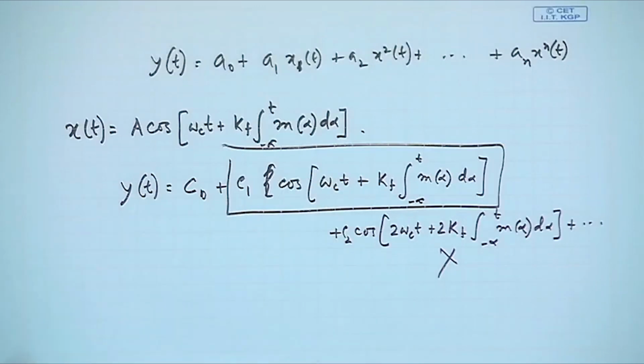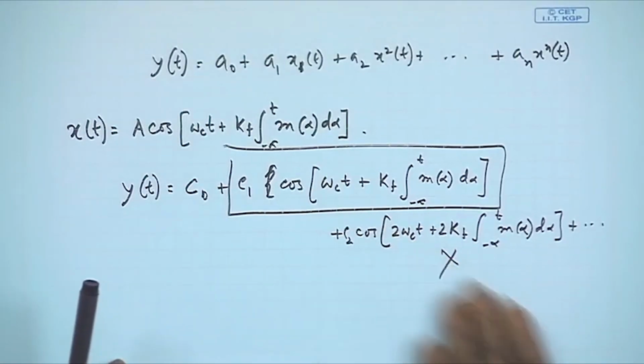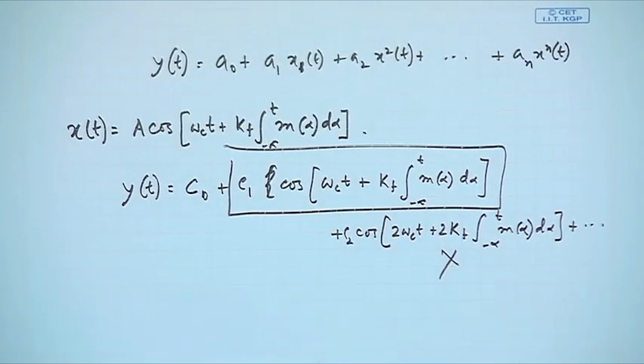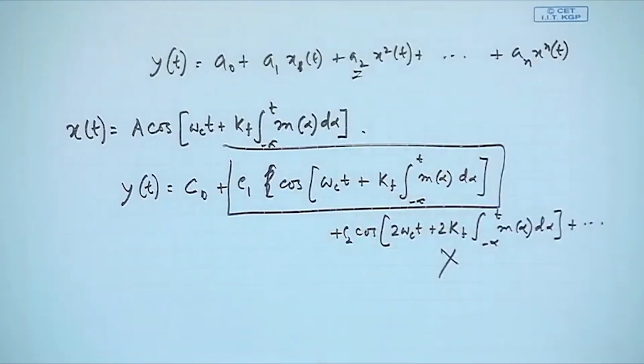We will see if there is interference. Whatever I have told is actually also a source of interference. If the channel is nonlinear and I have my FM signal at omega_c, but at 2 omega_c there might be some other FM signal, then due to these terms created in the channel, this will create interference to them. However small the nonlinearity is, the a2, a3 coefficients might be small, but they will still create some effect at those frequencies. Those are treated as interference.